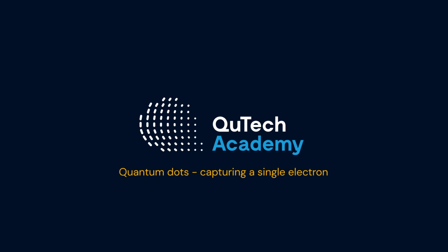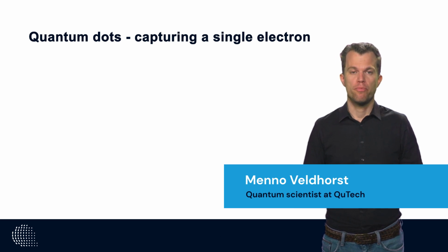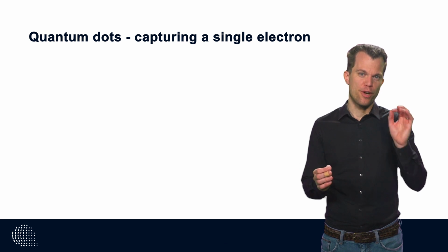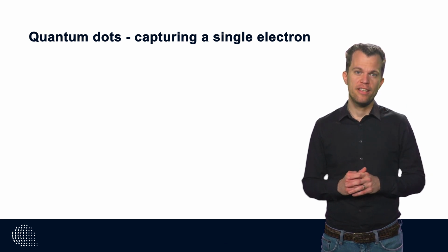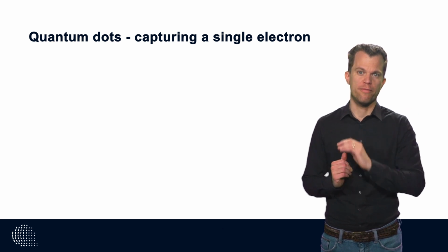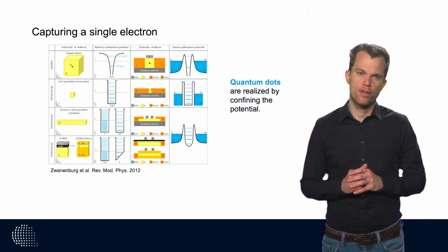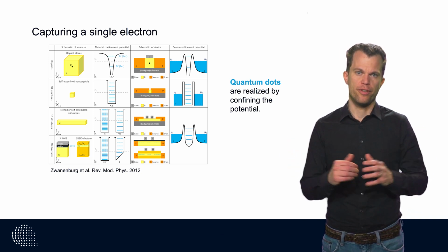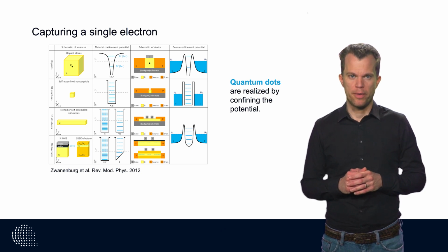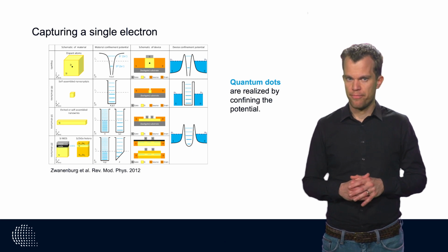While in an ordinary transistor, billions of electrons flow to provide a measurable current, in semiconductor quantum information, we are interested in operating and controlling electrons one by one. We do this by fabricating tiny metallic electrodes on a semiconductor material. Typically, a dielectric is placed in between the semiconductor and the metal to electrically isolate the two from each other.